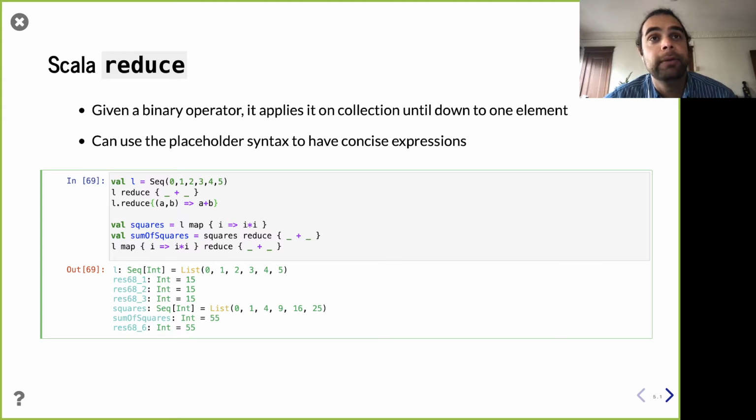For example, if I'm doing addition and I'm not growing the bit widths, rearranging a linear unbalanced thing into a tree actually is a different semantic behavior, right? Because now I'm performing accumulation in a different order, and it's not going to be the same.